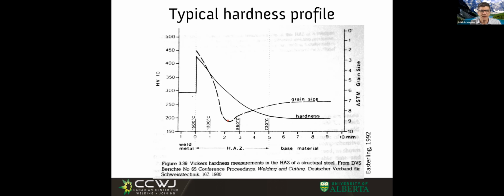And then it's funny, they talk about big grain size, right? And those of you who took an introductory course in materials would say, hey, isn't the story that big grain size tends to be softer and small grains tend to be harder?